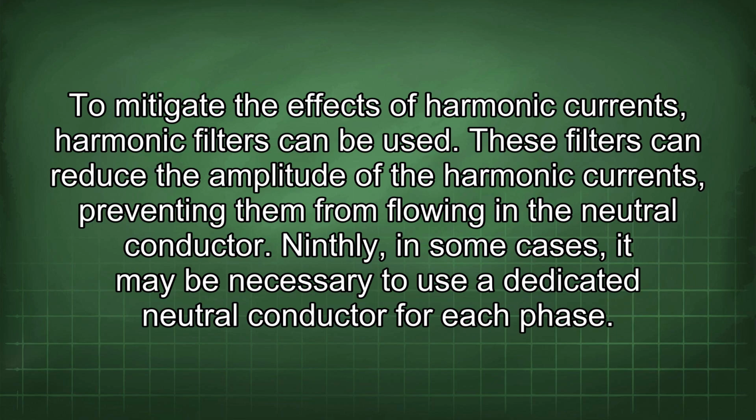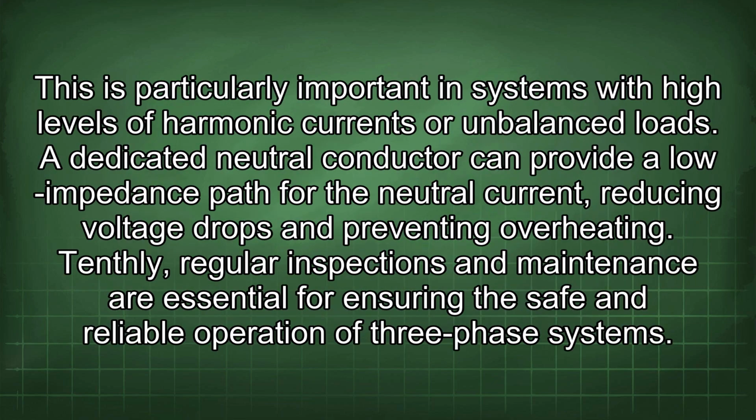Ninthly, in some cases, it may be necessary to use a dedicated neutral conductor for each phase. This is particularly important in systems with high levels of harmonic currents or unbalanced loads. A dedicated neutral conductor can provide a low impedance path for the neutral current, reducing voltage drops and preventing overheating.